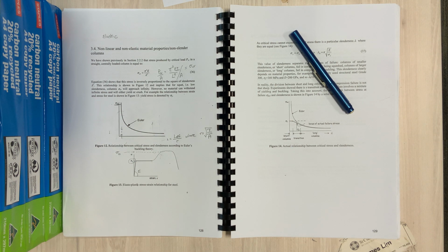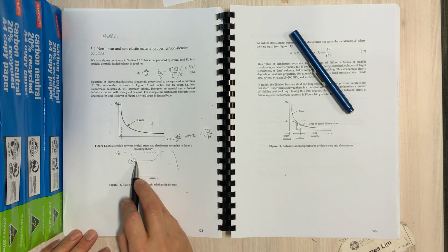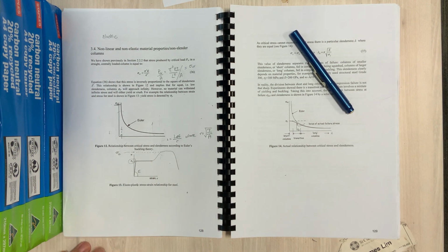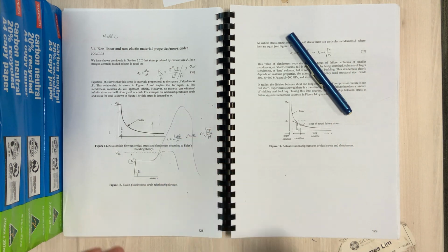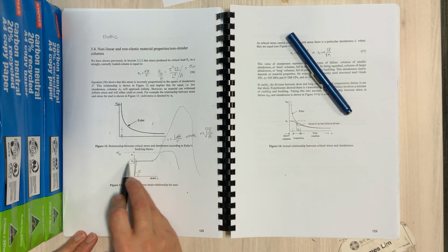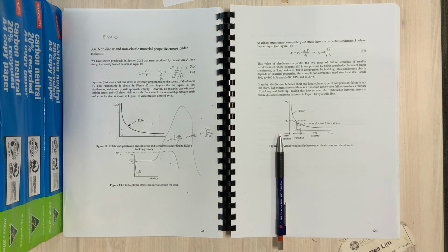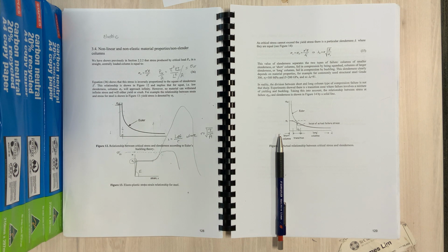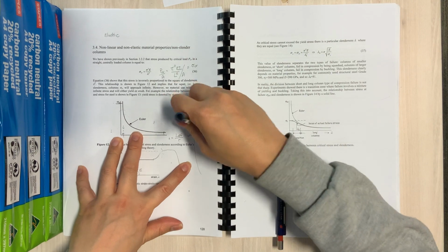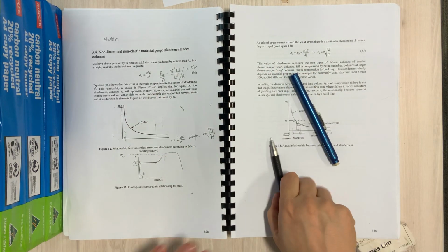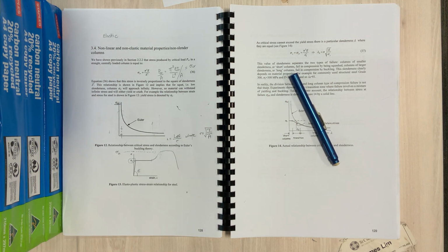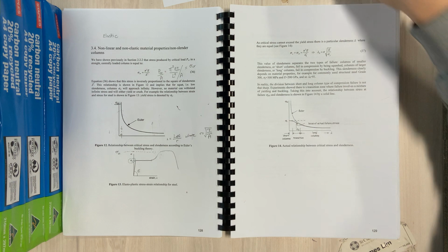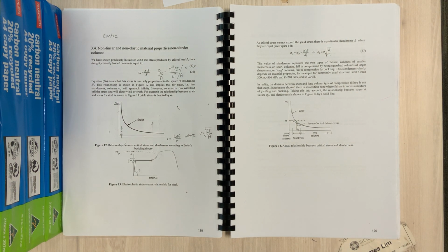And that's when your structure can buckle, because there's no strength. Here you've got E, and here the gradient is E, so it has some stiffness, and then here your gradient is 0. So no matter how high the ultimate strength can become later on, once you've reached this plateau defined by the yield stress, your column basically has it, and with zero stiffness your deflections would be shooting off to infinity. That's why we're only concerned with the yield stress, and why we're not talking about the rest of the graph that I showed in the experimental measurements.